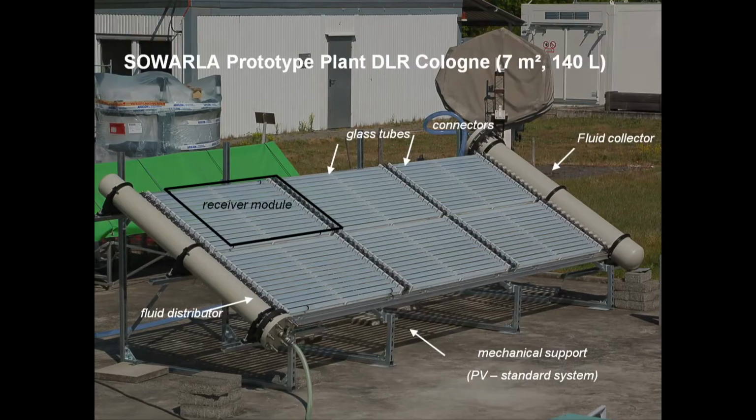We then scaled this up to our solar receivers, and we started to think about how such a receiver must look. It was important that the receiver modules can be handled easily, they must be rigid, they must withstand long times. As I told you, the plant in Madrid is already working for more than 10 years. So we designed these receiver modules out of glass tubes, and we added very efficient fluid distributors and fluid collectors to it so that we could guarantee a homogeneous flow through all the plant. We needed a simple but efficient stand, which we took from PV. So here is the connection to existing technology.